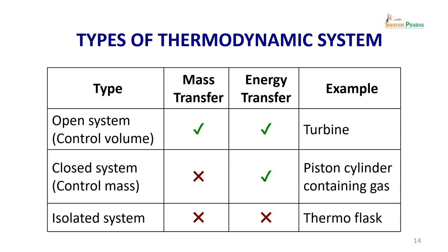A simple example is a fluid contained in a piston cylinder arrangement. Assuming that the fluid is taken through the suction valve and both the suction and the discharge valve are closed. Let us take 1 kg of fluid in a piston cylinder. I am compressing the fluid continuously with the help of the piston. As long as the discharge valve, or the delivery valve, is closed, there is no movement of mass of that fluid moving out of the system. So, here there is no mass transfer, there is only transfer of energy. Work is done on the fluid by the piston.